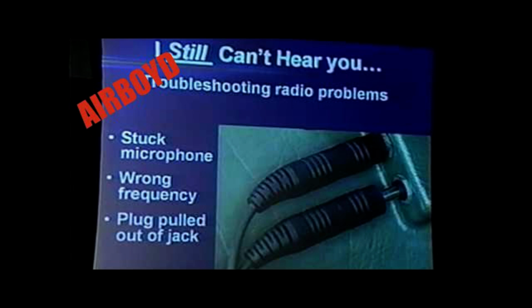Note, the exchange of information between an aircraft and an ARTCC through an FSS is quicker than relay via company radio because the FSS has direct interphone lines to the responsible ARTCC sector. Accordingly, when circumstances dictate a choice between the two during an ARTCC frequency outage, relay via FSS radio is recommended.